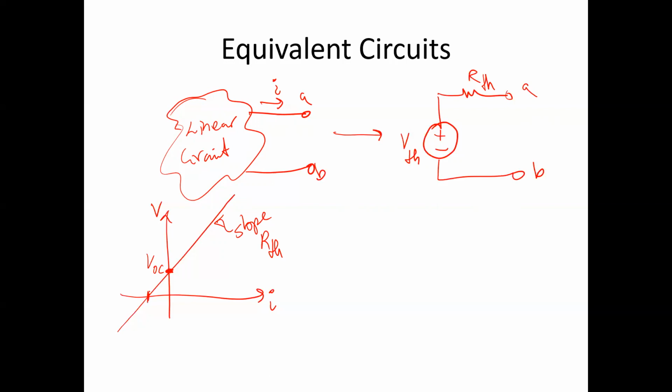And we also have a special label for what we have here, which is our short circuit current. This is the current that you measure when the voltage is equal to 0. Okay, so what we want to do is design a few subcircuits that will allow us to make this calculation. And so the first calculation is the open circuit voltage calculation.